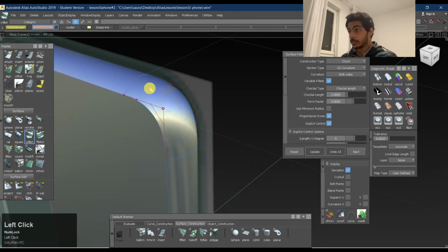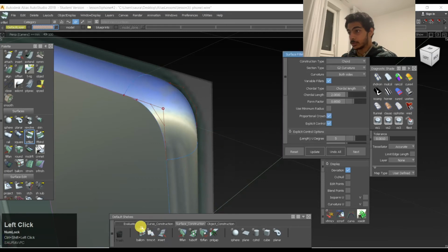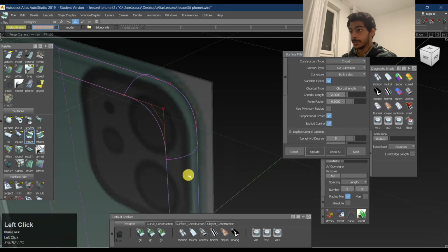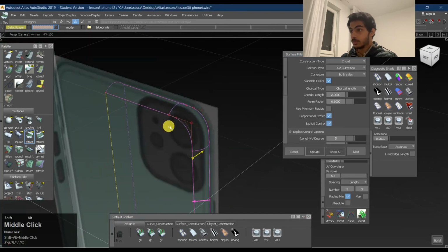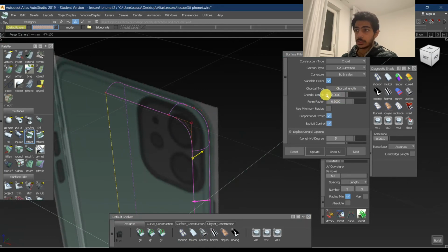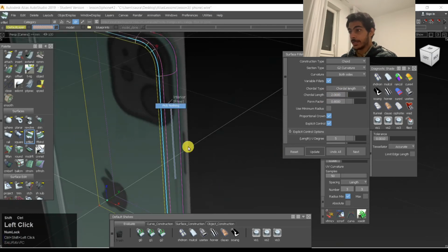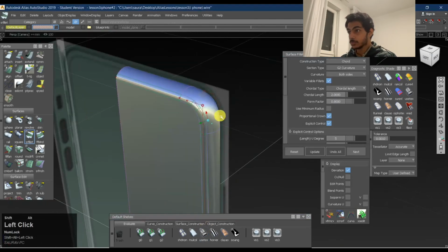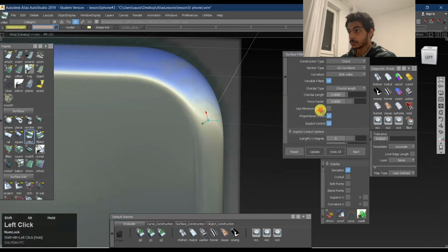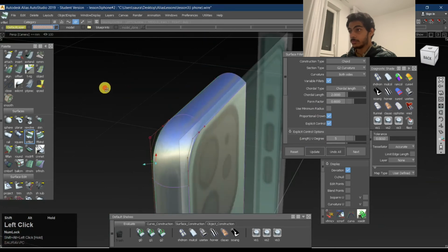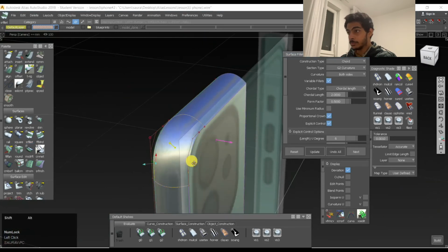So we select all these surfaces over here, 1, 2 and 3, and the fourth one with which we need to have a fillet, right? I already saw what worked with it. So it was around 2 mm. I press spacebar, keep it on edge align, and we have a small blend over here. It looks pretty good. The same over here.